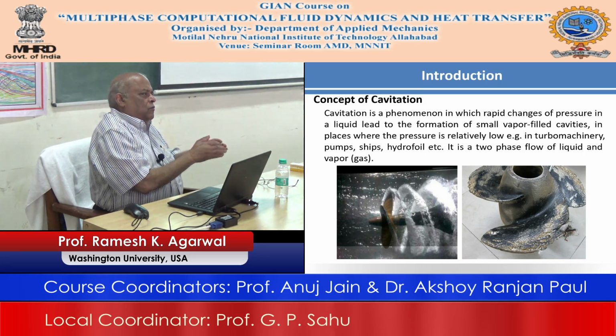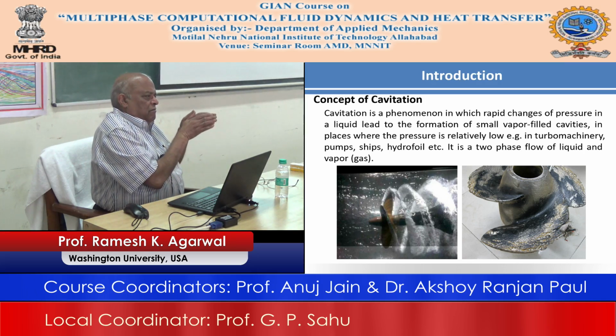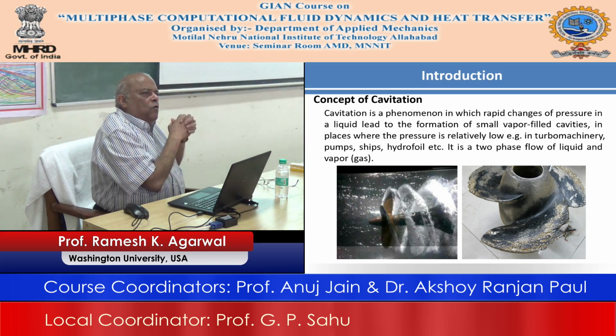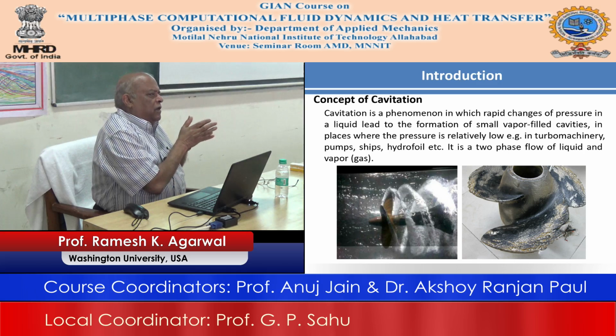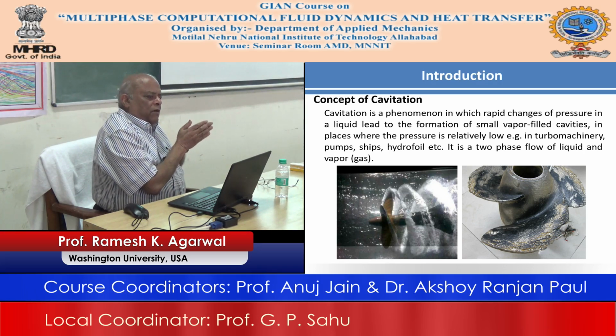They are internal flows, so they have a casing around them. If you have bubble formation on the blades, particularly at blade tips and between the casing, the flow becomes non-smooth, and it affects the vortex formation. All kinds of complex things can happen that can result in loss of efficiency.